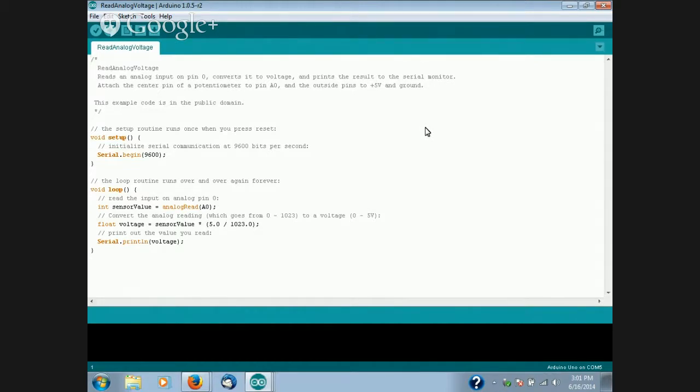Now, the smart coder, by the way, if you are speed limited, what you would do is define up here in setup, float cal equals 5.0/1023.0, and then you would... let's try this and then let me show you what that does. So first let's just try this.